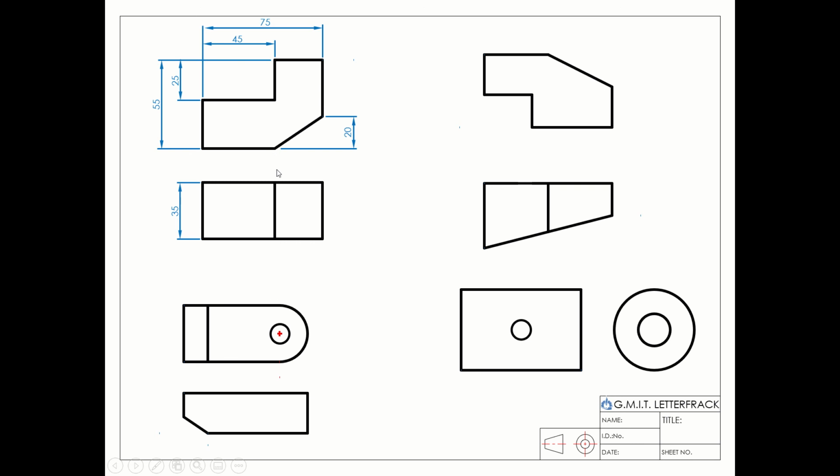But in that case, if you're reading the drawing, that takes a bit of working out. So you might actually be better off giving in the 30 millimeters there like that. Technically, that is kind of doubling up on something, but you are making the drawing much, much easier to read. So again, common sense should always prevail there.